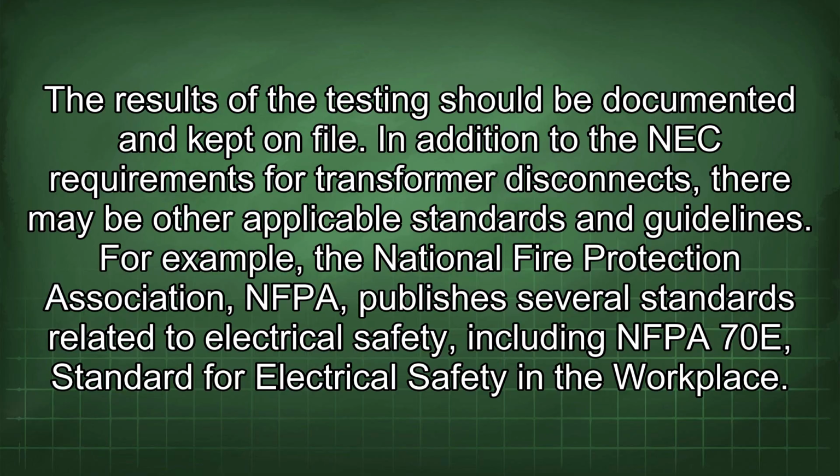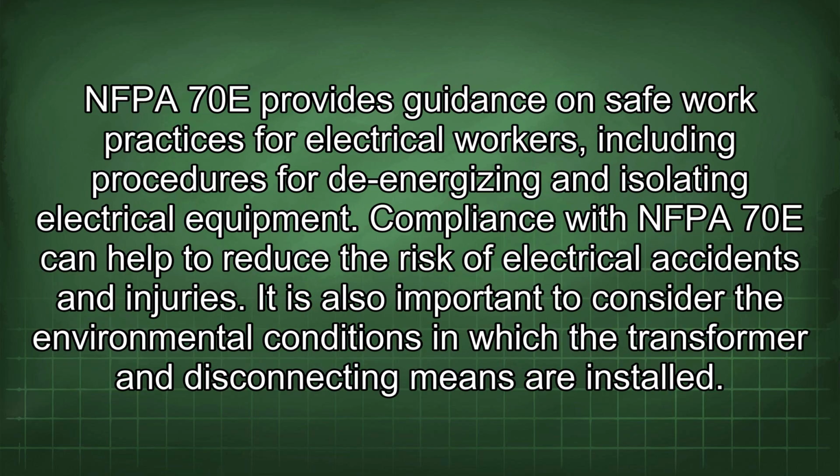In addition to the NEC requirements for transformer disconnects, there may be other applicable standards and guidelines. For example, the National Fire Protection Association, NFPA, publishes several standards related to electrical safety, including NFPA 70E, Standard for Electrical Safety in the Workplace. NFPA 70E provides guidance on safe work practices for electrical workers, including procedures for de-energizing and isolating electrical equipment. Compliance with NFPA 70E can help to reduce the risk of electrical accidents and injury.